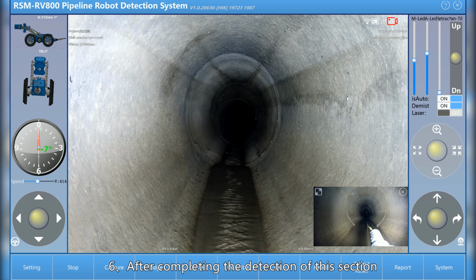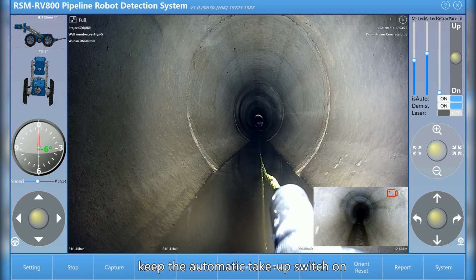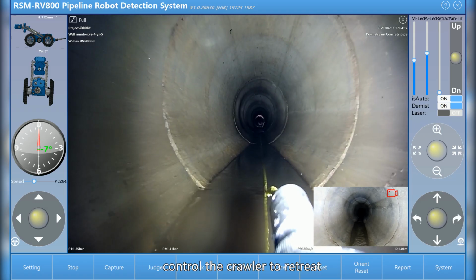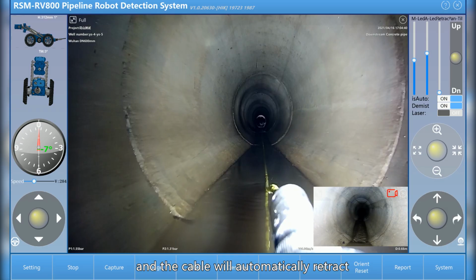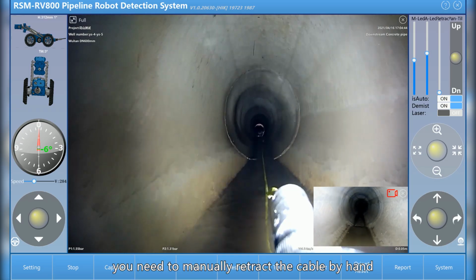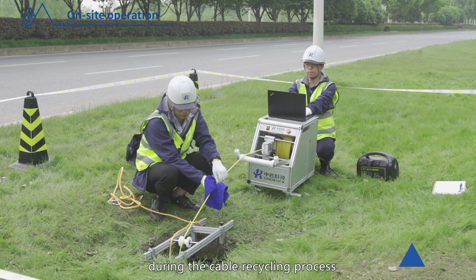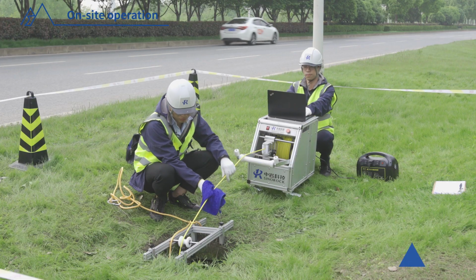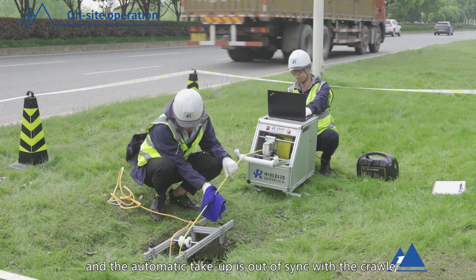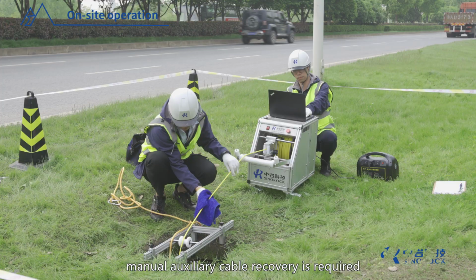6. After completing the detection of this section, switch the rear view interface. Keep the automatic take-up switch on. Control the crawler to retreat and the cable will automatically retract. If it is a manual winding car, you need to manually retract the cable by hand. The cables can be cleaned during the cable recycling process. If the situation in the pipeline is complicated and the automatic take-up is out of sync with the crawler, manual auxiliary cable recovery is required.